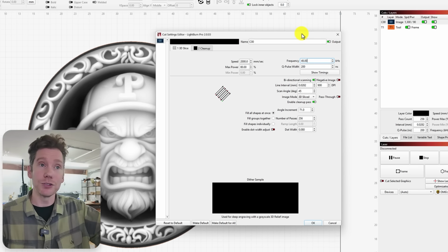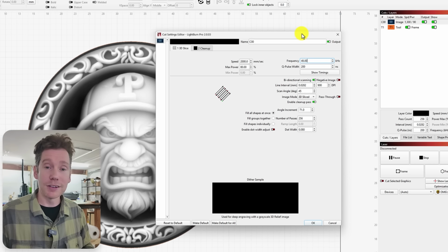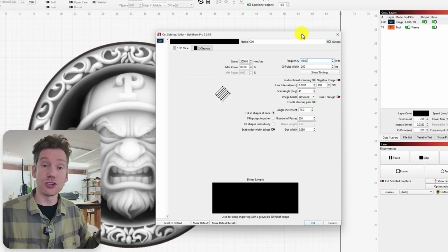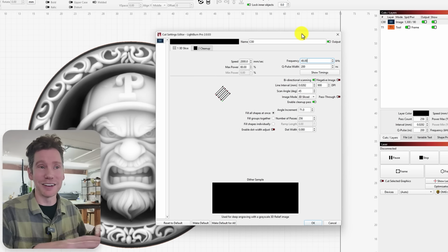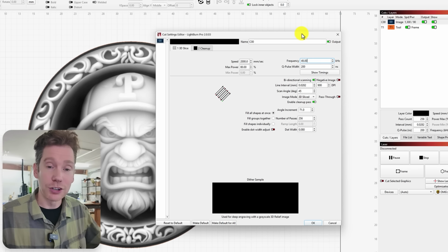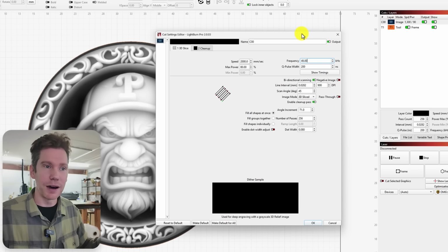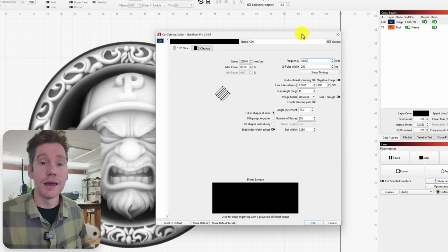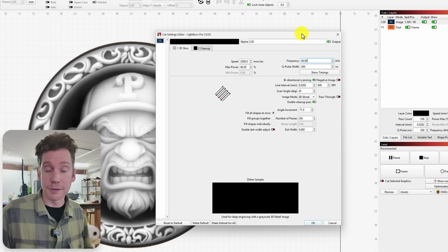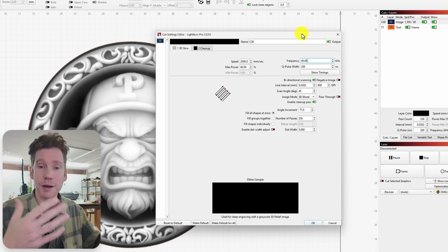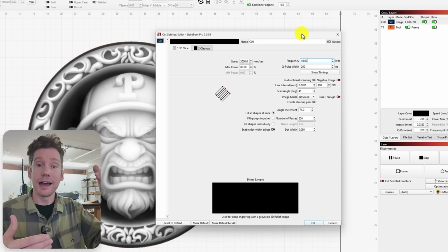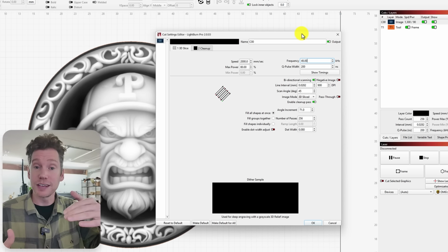especially if you put a number that's too low in there. So if I were to put 20 in there, my laser is going to be like, hey, you're asking me to generate and store a lot of pulse energy. And I don't think that I can stably do that without potentially damaging the insides of your laser parts. So what the controller does, it's kind of like the safety monitor, the hall monitor of your laser, it starts to scale your power down. And there's a whole chart you can find depending on your manufacturer that tells you exactly how much you're going to scale your power down.